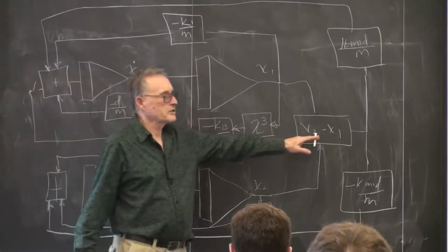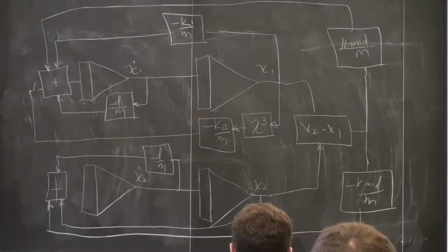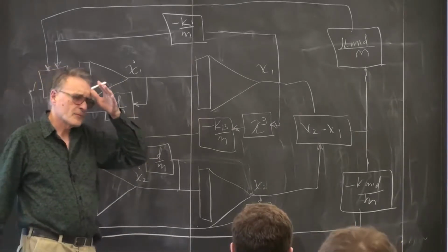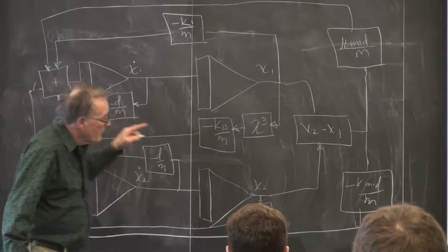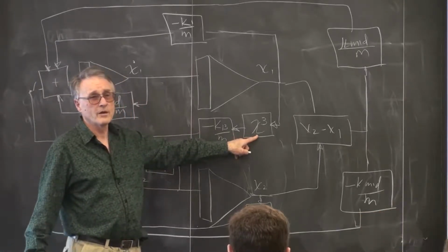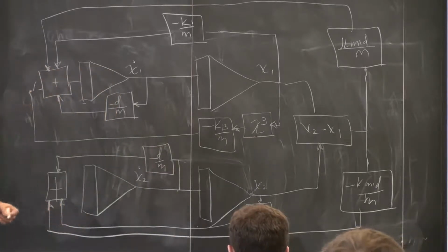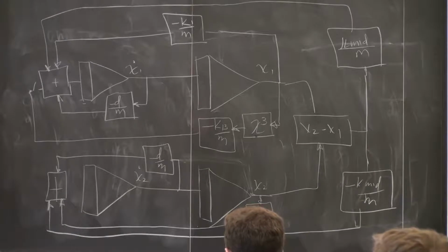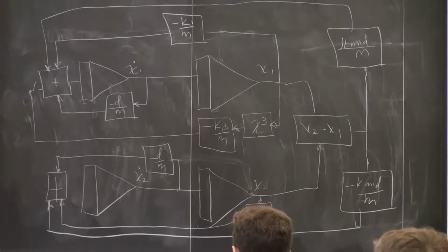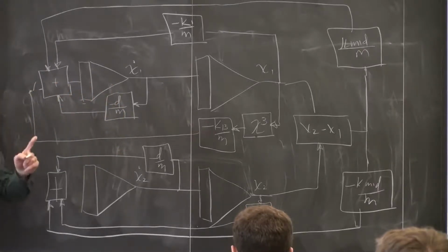So the subtractions you can just do in line, of course. The sums you can do in line. The multiplies are all by constants, except for this one where you have to take the product of the variable with itself twice. And so you have a fairly good list of modules, so you need to come up with a naming convention for the signals coming out of them that makes sense to you. This is what you're going to put together and then test in Modelsim.